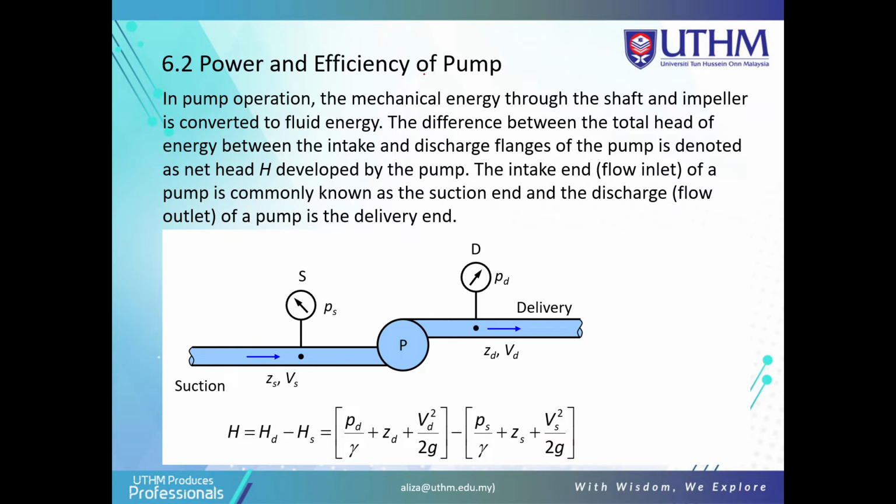Power and efficiency of pump. In pump operation, the mechanical energy through the shaft and impeller is converted to fluid energy. Based on this pump, the suction is here, the flow goes through the pump, and it is delivered to here. The difference between the total head of energy between the intake and discharge flange of the pump is denoted as net head, H, developed by the pump. The intake and flow inlet of a pump is commonly known as the suction end, and the discharge flow.